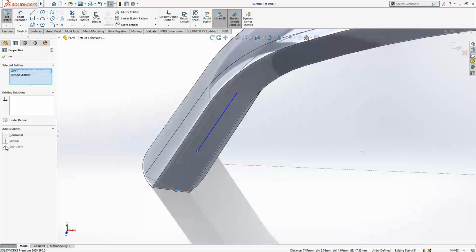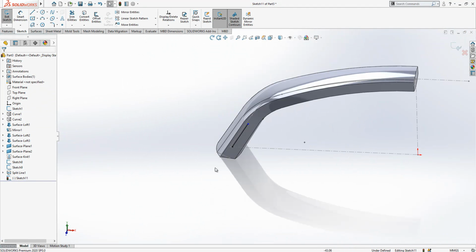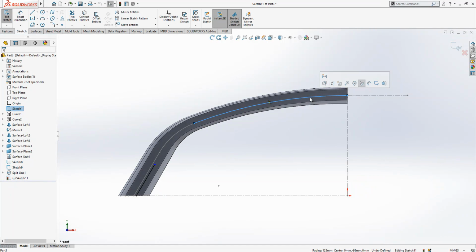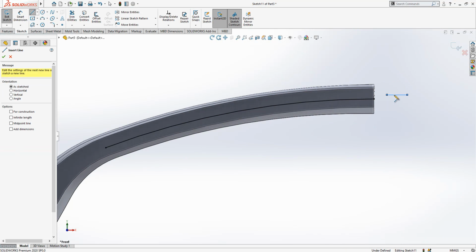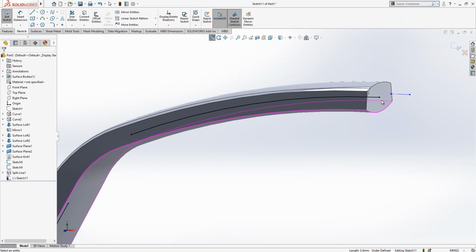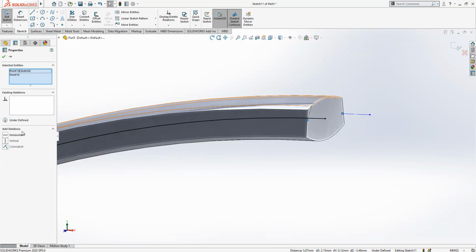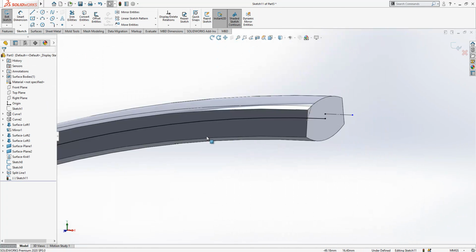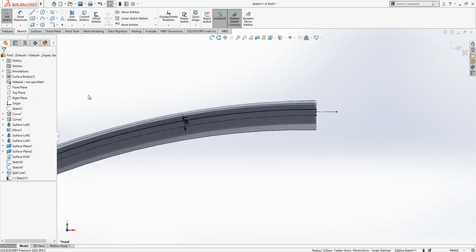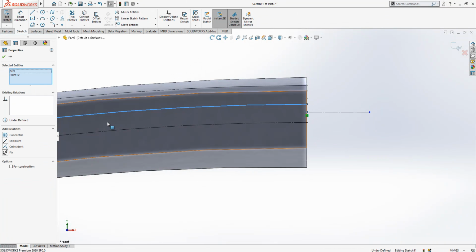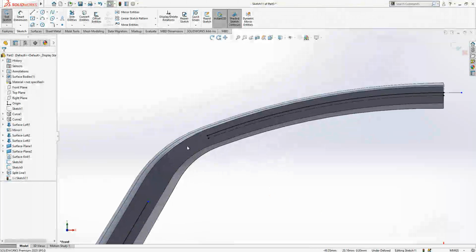I created a new sketch and I make here a coincident. This is looking nice. Convert entities, select hide original. So right click and here create a construction geometry. So again, we met with a line on the point that we would like to end up. So this was an offset, make it construction geometry, offset entities, just one is enough now. And I come here, delete the dimension, just meet this point. So this is as well good.